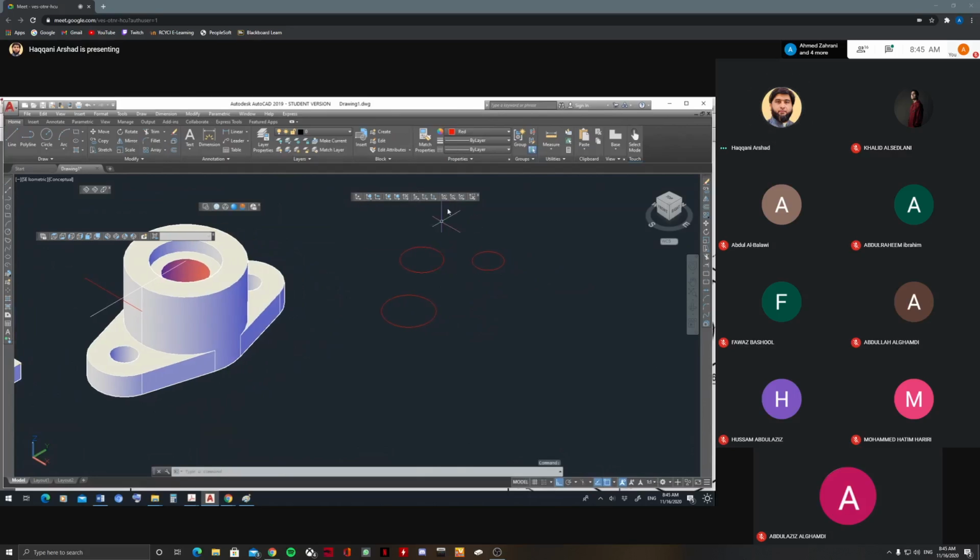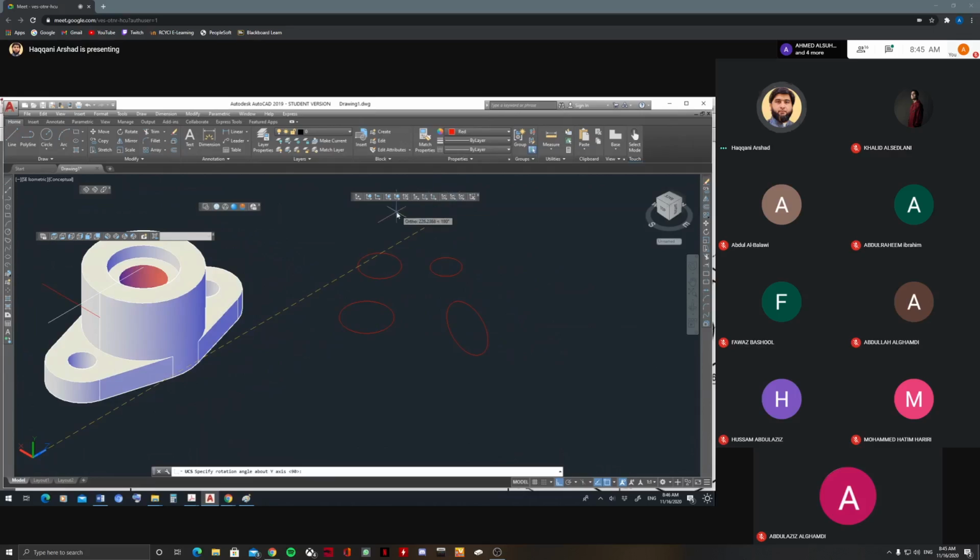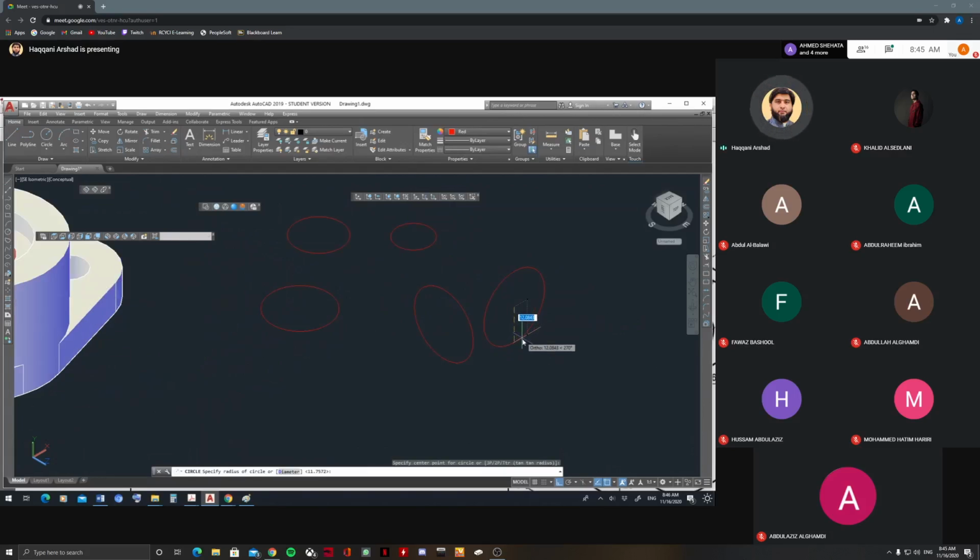For example, if I select X rotate here, click this one and enter, and when I try to draw a circle, see, it is coming on the left side. Then if I go for Y rotate, enter, when I click the circle, see, it is coming on the right side. So this will allow you to draw any object, not just a circle, any line or any object on either side, maybe top side, on the left side, on the right side, like this.